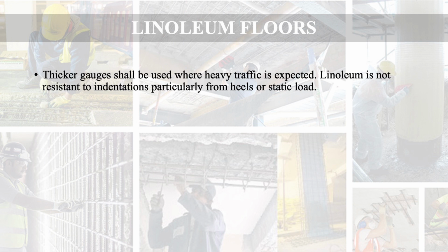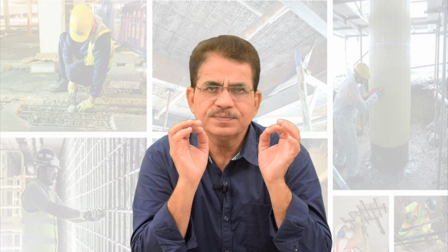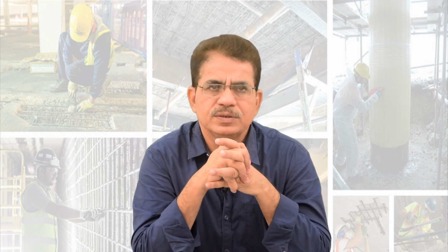Linoleum is not resistant to indentations. Keep in mind, it is not resistant to indentations, particularly from heels and static loads. Linoleum, when highly polished or wet, can become dangerously slippery. This is the great problem, that if it is wet or if it is polished, then it is very slippery. So accidents may occur due to a fall while walking over such floors.